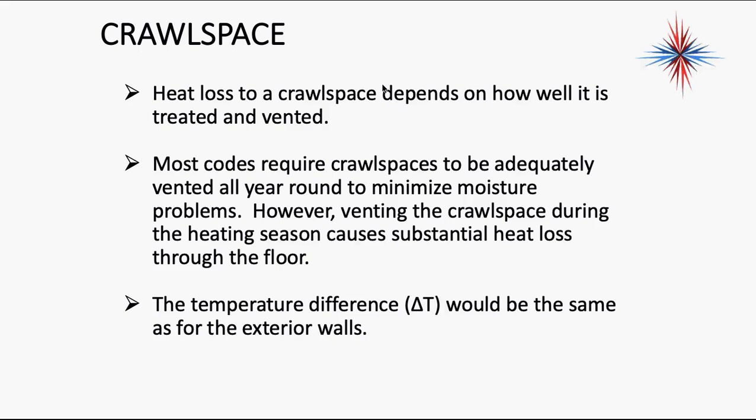Floors always feel cold. My dad lives up in Vermont, and when he first bought his new condo, one of the things we had to do was go up and insulate the crawl space because all the insulation fell out and was sort of moldy too. But again, cold floor areas, if the crawl spaces are not insulated, tremendous heat loss. The temperature difference between the floor of a crawl space would be about the same as for exterior walls.